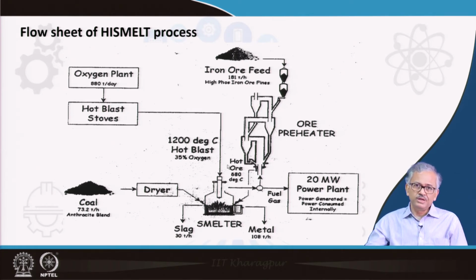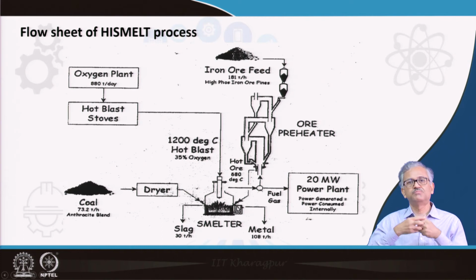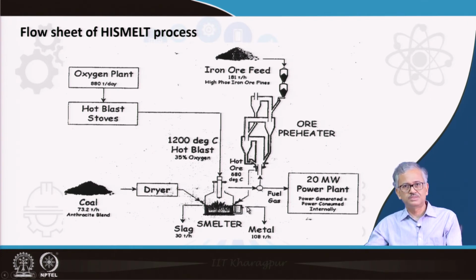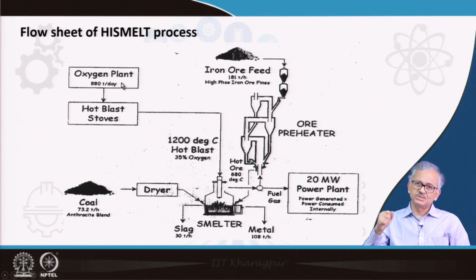So coal rate will decrease from two counts. One thing is because of the preheated air blast. Second is that since you are injecting it, the process efficiency becomes much faster. Melting of the iron ore becomes faster, and then coal gasification and the coal oxidation also become faster. So basically the process becomes efficient, your coal also decreases. Also the preheated air blast, that also decreases coal. And also a large amount of oxygen is not required. So the oxygen plant will be only for enrichment purpose.